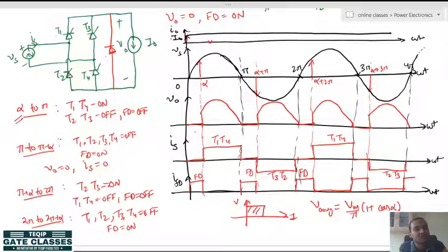Now, one thing you observe is that the output voltage is not getting negative, but this is coming at the cost of 2 additional thyristors. If you are putting 2 additional thyristors, your thyristors are not being utilized fully. So we should avoid using such a costly circuit. If I have to use the circuit only in a single quadrant mode, then why go with this costly circuit?